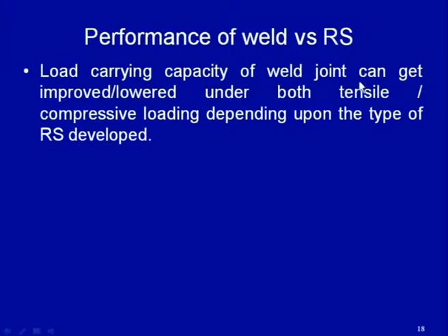Now, we will see how the performance of the weld can be affected by the residual stresses. The load carrying capacity of the weld joint can be improved or lowered under both tensile or compressive loading, depending upon the type of residual stresses that are developed. So, residual stress development can increase or decrease the load carrying capacity of the weld joint.